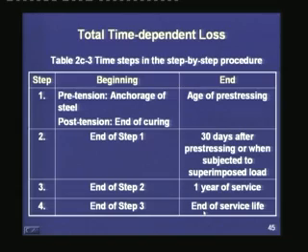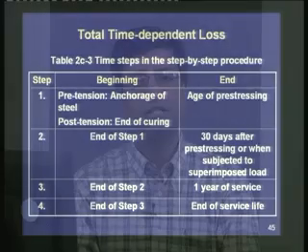To summarize, creep, shrinkage, relaxation, they are related to the drop in the pre-stressing force. If we calculate the losses individually and add them up, that is an overestimate of the total pre-stressing loss. For important structures, we need to do a more precise calculation considering the interaction between the creep, shrinkage, relaxation and the drop in the pre-stressing force.